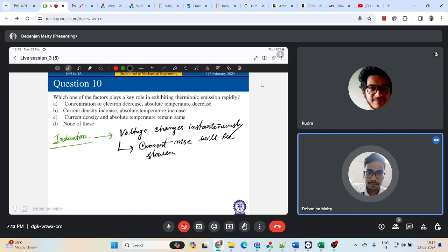So it is important that there should not be any rapid current increase, or what we call a current surge, during that short circuit, and this would basically result in some kind of electromagnetic force which will cause spatter and oscillation on the surface of the weld pool. That should not happen, right?